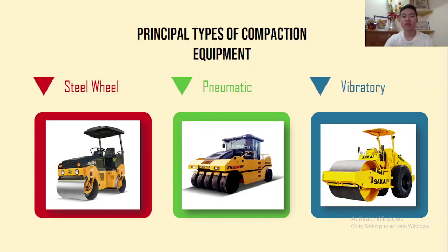When it comes to pneumatic rollers, sometimes called pneumatic tire rollers, these are a type of large ride-on roller with several rows of rubber tires on the front and rear end. The rubber tires provide an 80% coverage area and uniform pressure throughout the width of the tires. They are typically used for pavements and can help smooth out and polish a project, but are also great for cold laid bituminous or cold laid mixed pavements and layers of loose soil.